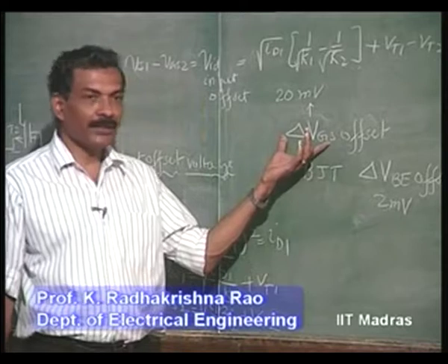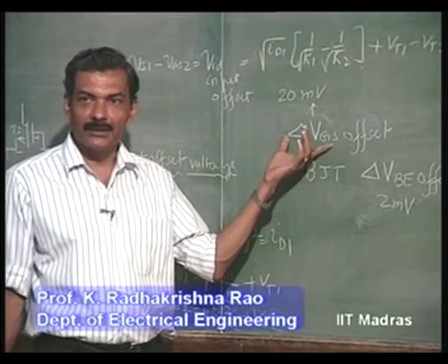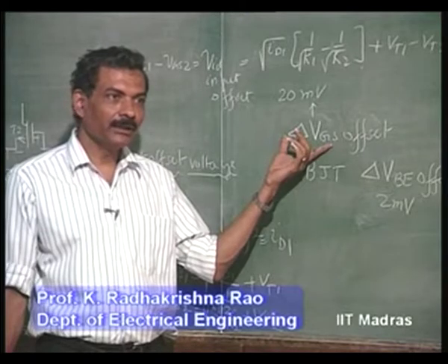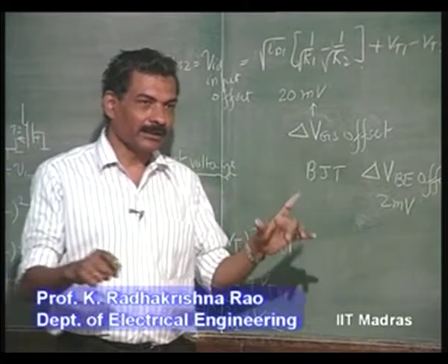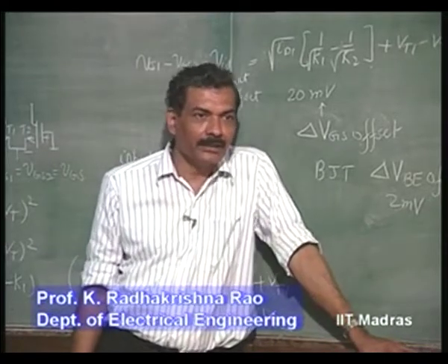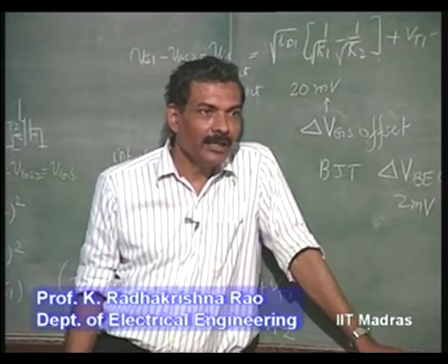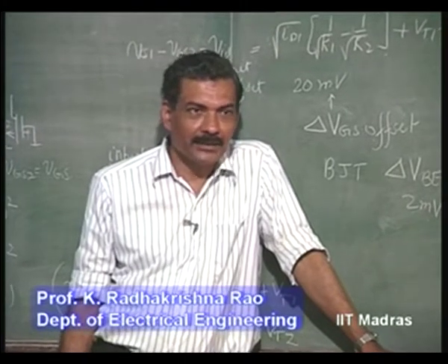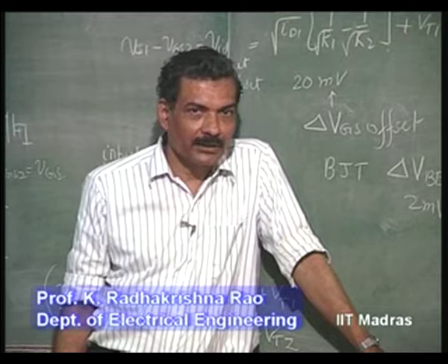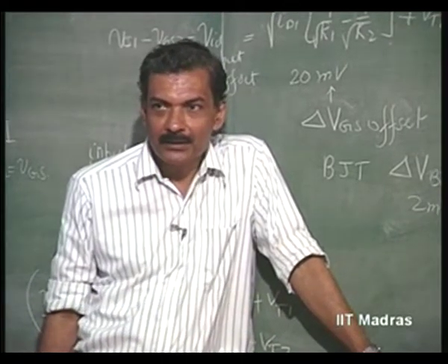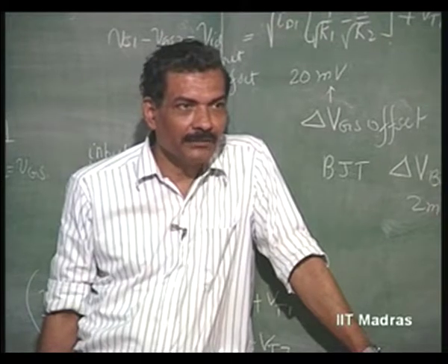This is the configuration with the highest input impedance, infinity, right? And there you have maximum offset. This is the case with any amplifier configuration. If you try to increase the input impedance, input offset will increase, right? There is always a price that you pay somewhere or other. So, when you try to increase input impedance by any means, the input offset voltage will increase.